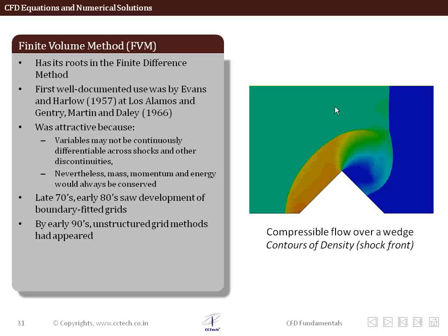The differential form of governing equations is actually derived from the integral form, assuming that your flow quantity is continuous. Now, as you know, in a shock wave, things are not really continuous. Things have a sudden drop or sudden change in properties across the shock front, and therefore we cannot afford to have this assumption being applied. So in this case, the differential form of governing equation doesn't really hold, which is what is required for the finite difference method. So we'll discuss this later on, as we'll see in the forthcoming slides.